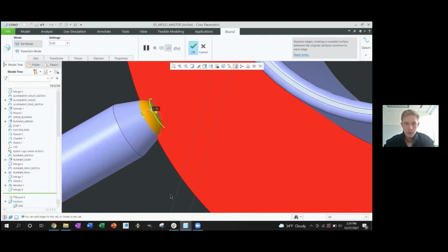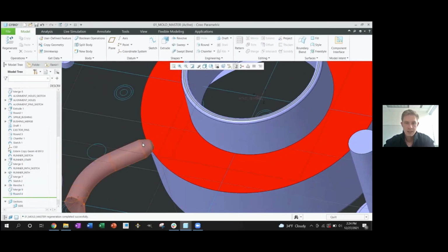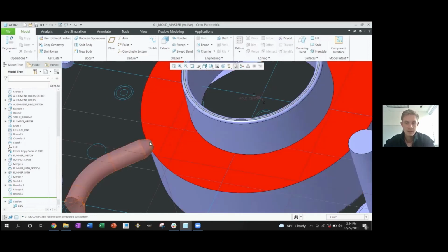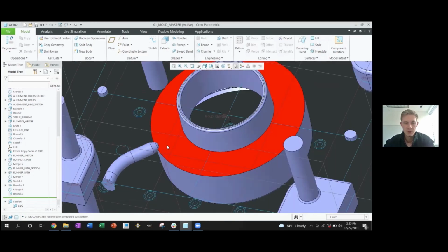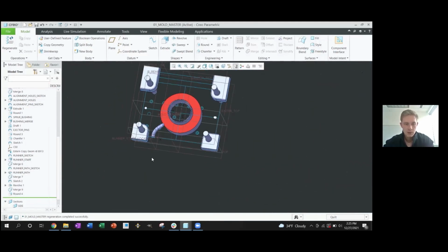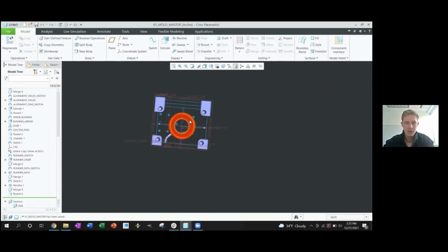try 1. So essentially what that's going to do is it's going to allow the plastic, instead of hitting a sharp wall at the end of the gate section on this top half, it's going to allow the plastic to kind of angle itself and flow itself into the part, so you don't have any sort of stress buildup at that location. Great. So at this point, our master model is done. We're ready to go ahead and design our part.